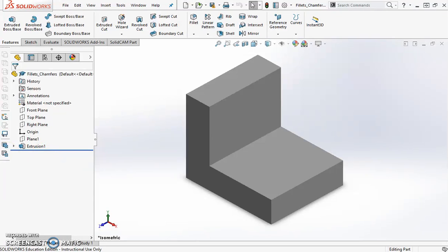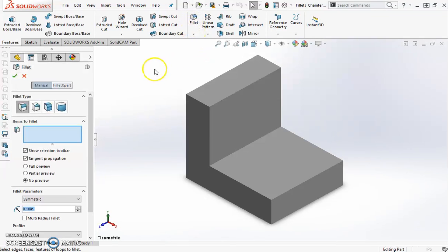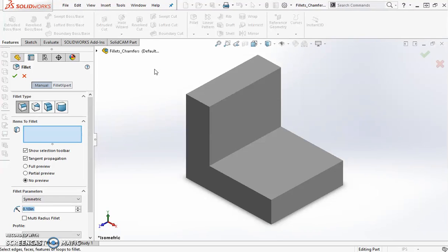This next activity is 2 parts as well. This is the Fillet tool and the Chamfer tool in 3D, not in 2D. So in the 3D features tab, fillet and chamfer are actually underneath one another. So fillet works just on curving an edge. So here you just pick what you want. So let's just do this edge right here.